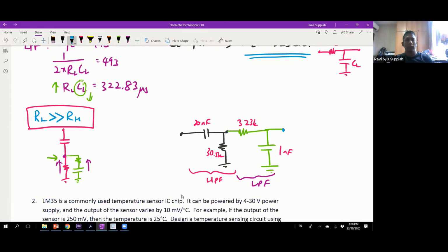But as what we have seen in the lab, it is always good to connect it with the op amp, so that when you attenuate what you do not want, at the same time you are amplifying what you want. The whole idea of filtering is you remove what you do not want, but at the same time you also amplify what you want. The reason you amplify it is because when your signal becomes bigger, it uses a bigger range of voltages, which means that when I do sampling later on, it will help me get a bigger range of values.